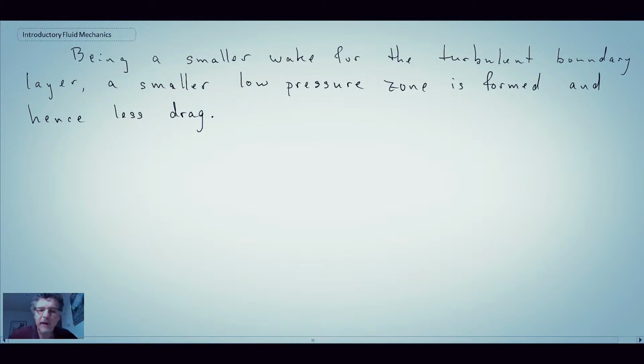So what happens, we have less drag due to the fact that the boundary layer is energized when it is turbulent. And I'm sure you're aware of this, but if you're not, it's the reason why golf balls have dimples in them. What the dimples do is they cause the boundary layer to transition, and when it transitions, it goes from laminar to turbulent. It'd be the dimples on the front of the ball that are causing the effect, but it's basically surface roughness.